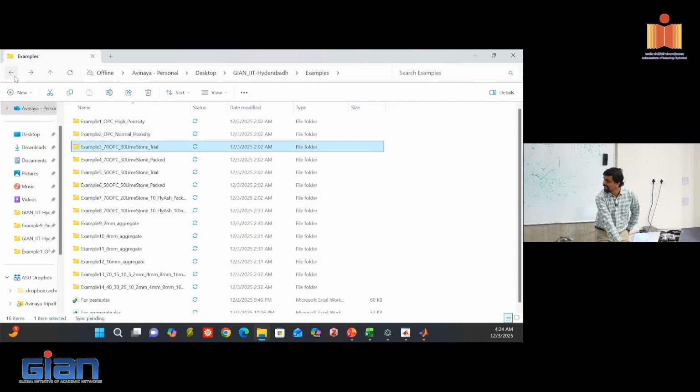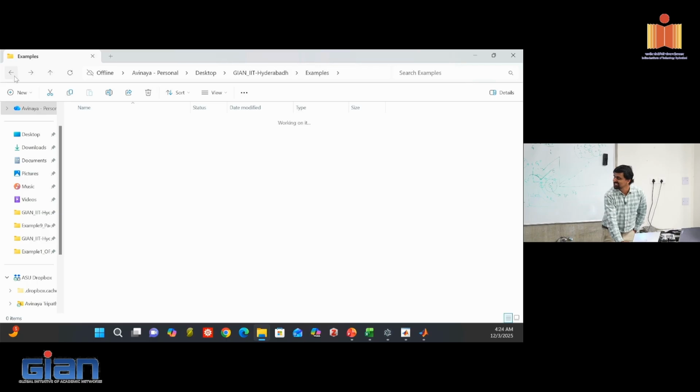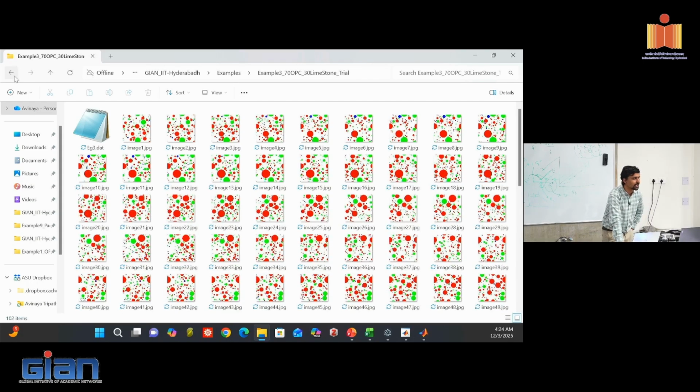So again, I have this for the limestone one. This is one of the other printable mixes that we had. This is L30, meaning 30% limestone, 70% OPC at 0.35. I had the calculation written on a paper, but the volume percentage of water was 52%, I guess, 51, 52% by volume. In OPC, I had to go to 0.4 water binder ratio, so I was at 56 percent volume. With L30, I am at 52 something.